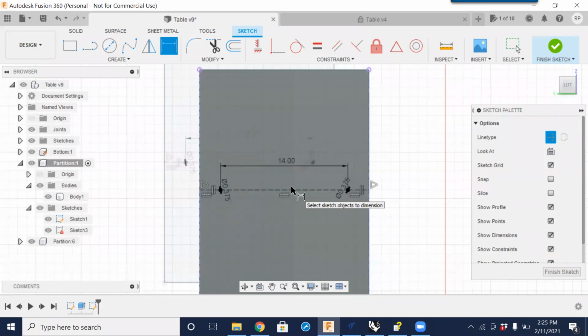Now the challenge that you'll run into dimensioning the way I have it right now is, remember we've set the width of this to also be a variable. So if at any time through reduplicating or resizing, the size of this part becomes less than 14 inches, our holes are now going to be on the outside of the part. So it's not going to work out so well.